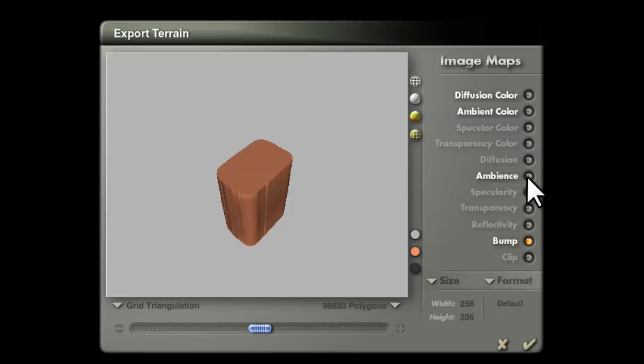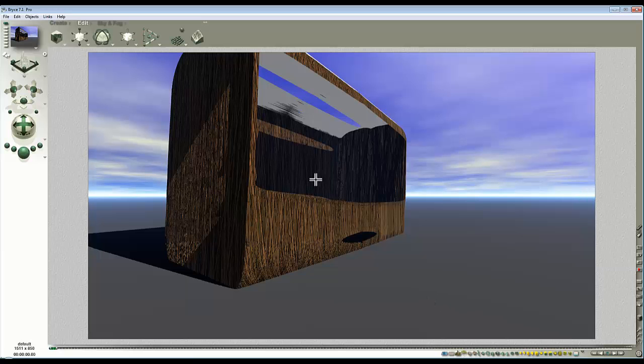You don't want Bryce to make any materials with this because it'll slow the process down for exporting. You're going to bring this back in and you can just transfer the material across from your existing lattice. So here we've converted our symmetrical lattice into a mesh object. Save that. Conversion is fairly quick in this case. If we'd chosen to include the materials, it could have taken quite a while, and the material conversion is not very good from procedural into image based.